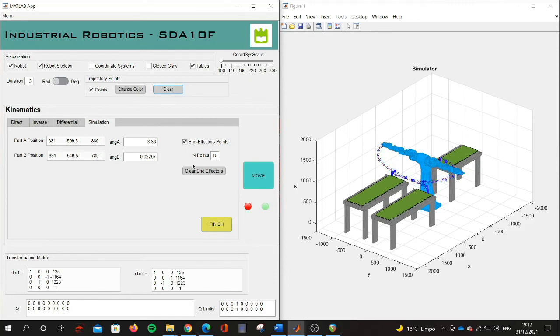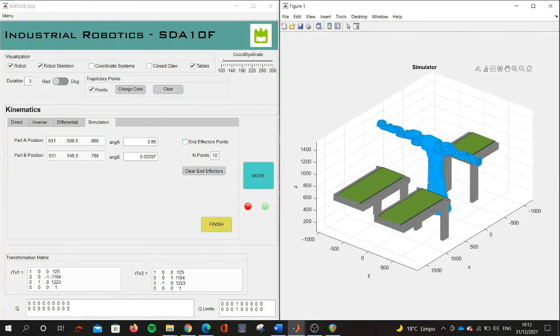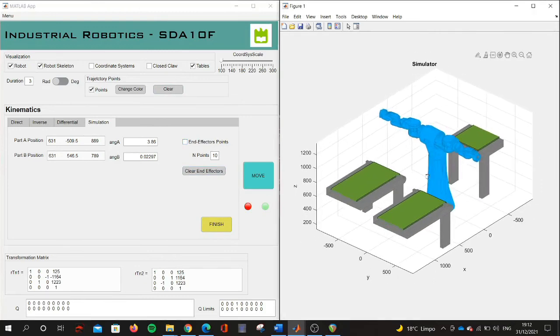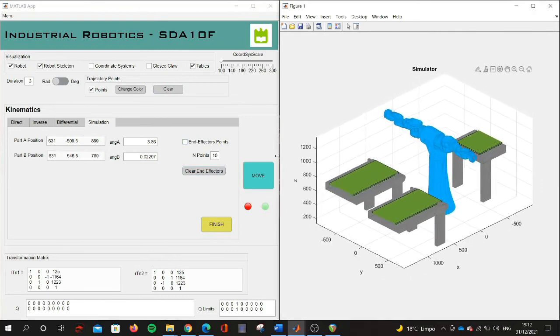Then, we will use a linear approximation to the part and the gripper will close. The robot will go up with a linear movement, then place the parts in a near position and join them with a linear horizontal displacement. With direct kinematics, we can get joint 0, the body of the robot, to rotate 180 degrees, and finally, it will go down, open the gripper and go up, all with differential kinematics.